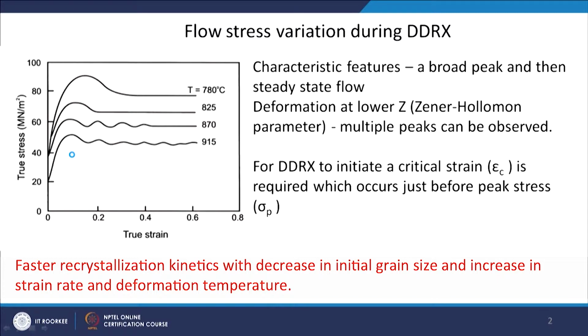You can see that when you have discontinuous dynamic recrystallization, the stress-strain or flow stress curve has this kind of a peak, and then it comes down and more or less becomes a steady state. As a function of temperature, as the temperature increases, the flow stress reduces. You can also see that this hump or peak is of lower magnitude.